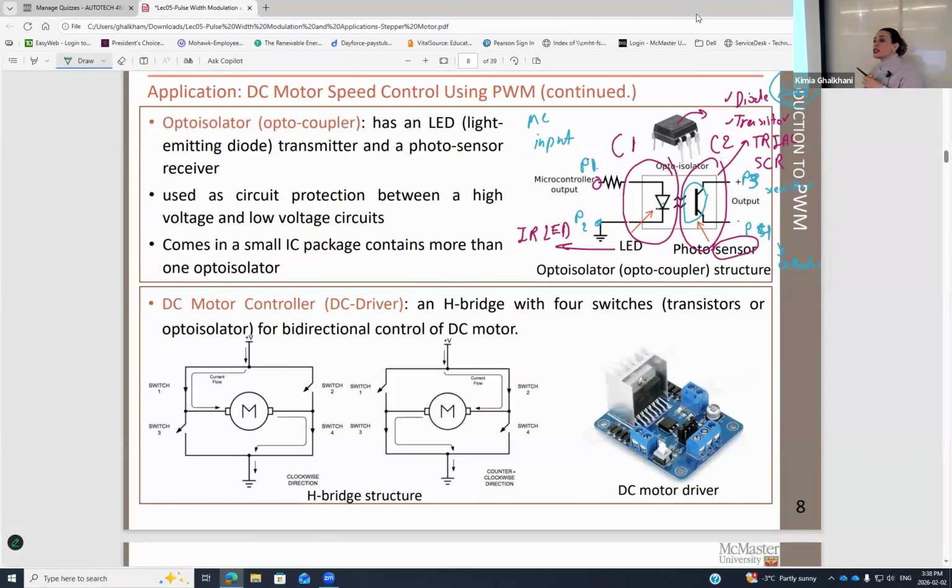Now tomorrow, when I tell you to connect your optocoupler to pin 4 in case you are using channel A, and then the ground, you now have that understanding of what I say. You don't need me to explain it anymore. You know that either pin 7 or 4 could be the input from the microcontroller.